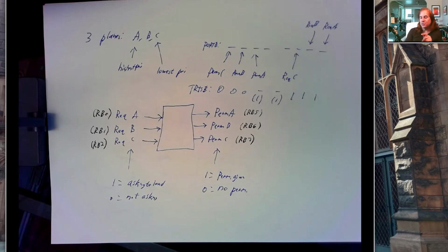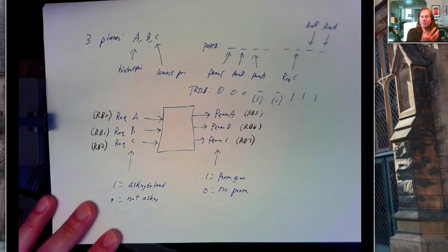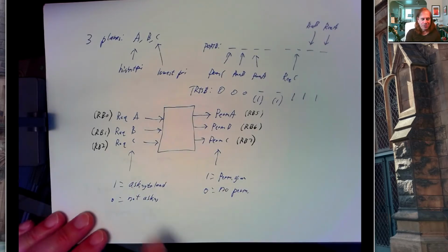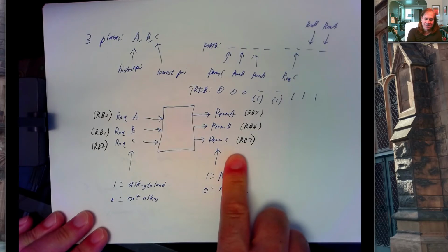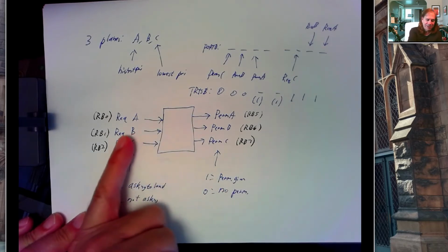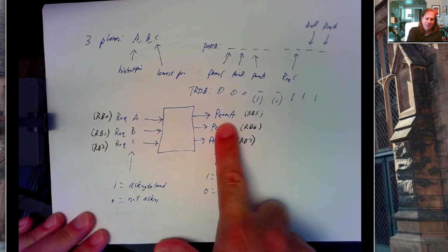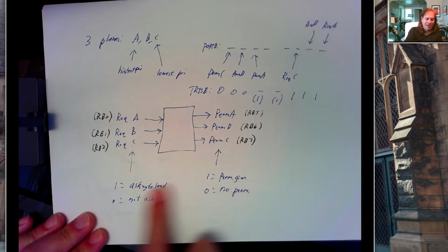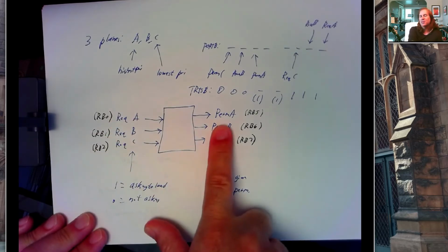But once you think your code works, sometimes it's nice to be able to step back and see it at a larger scale. And so, in a physical lab, what we would do is take a proto board and a physical PIC chip, program it with our code, put the board into a circuit, and hook up 3 switches for these requests and 3 LEDs to these outputs. And then power up the chip, and you could flip the switches. You could say, okay, let's flip this switch to a 1, and we'd see permission A come on. And then we'd flip this to a 1 and a 0, and we'd see permission B come on. And we'd flip all 3 switches on, and we'd see permission A come on, and so on.